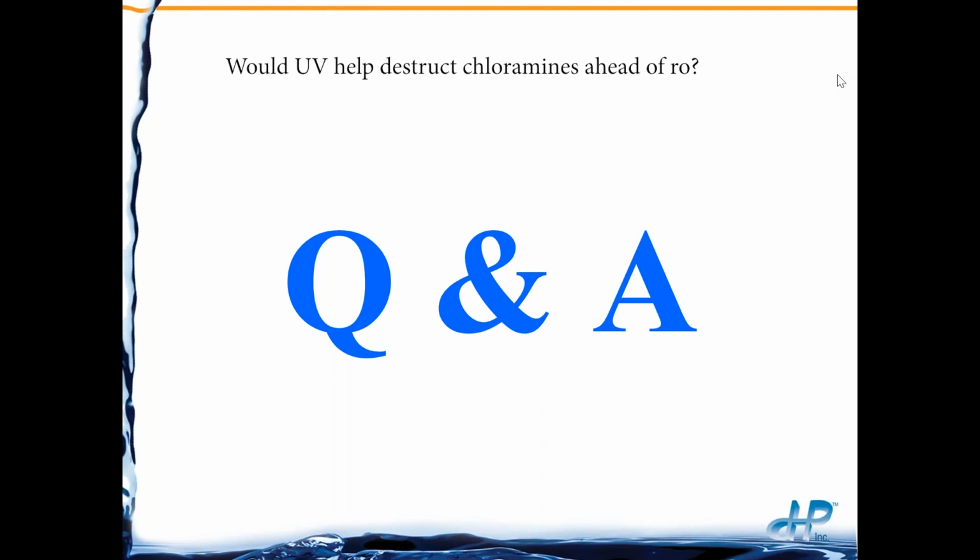Whereas for chloramines, the RO membrane may have 100,000 ppm hours of tolerance. So chloramines do not have the same oxidative power as free chlorine. So if you have chloramines going into an RO membrane, unless you have iron laying on the membrane, it is not going to be an issue.